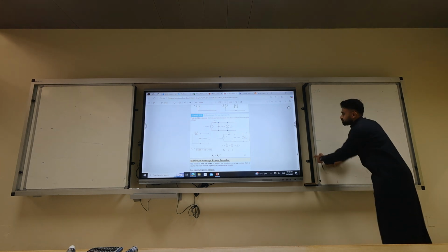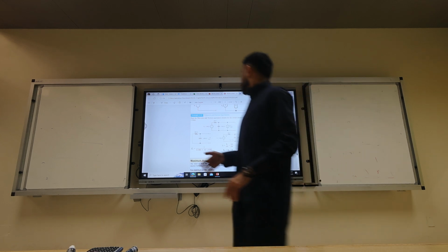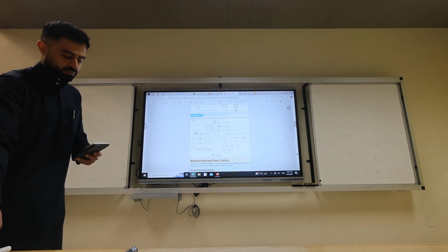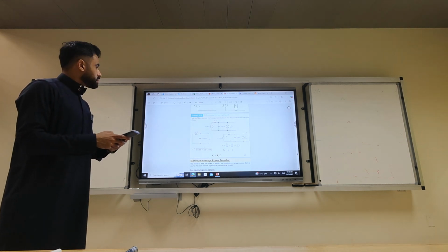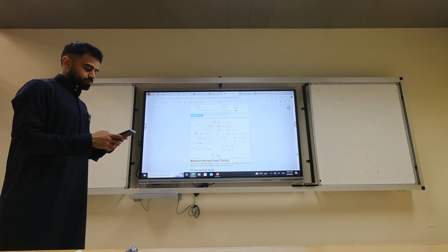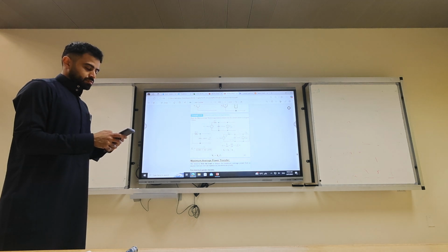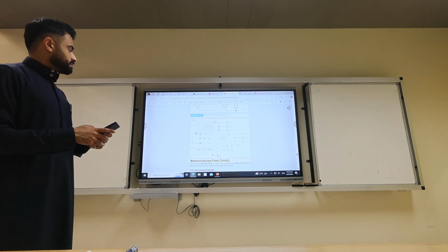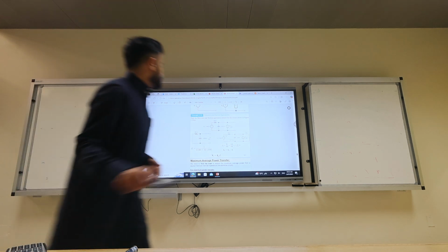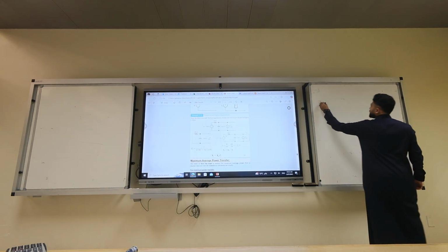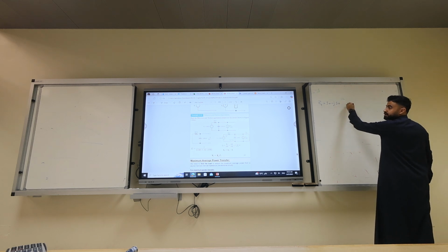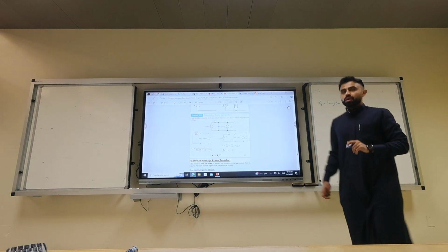It's what? 100 inverse plus. It's 50 minus 50J, right? So Z Thévenin is 50 minus J50, right? What's the unit? Ohm. Here we did calculate Norton equivalent, not Thévenin.